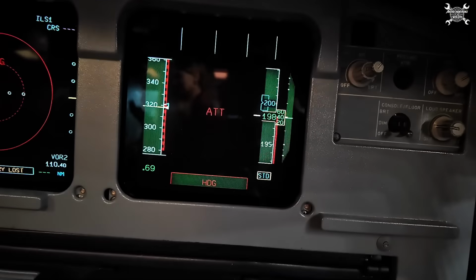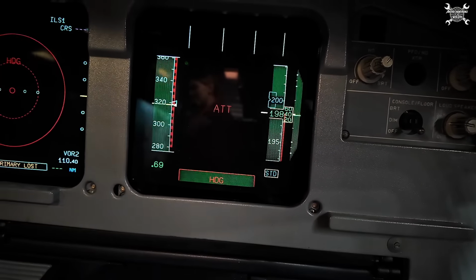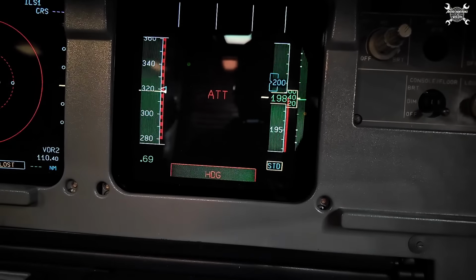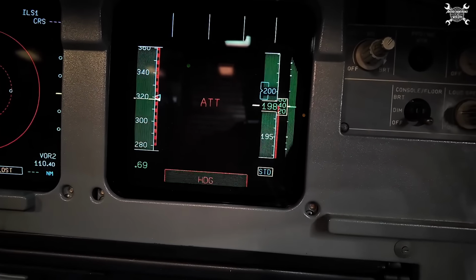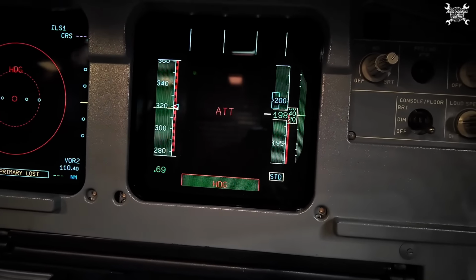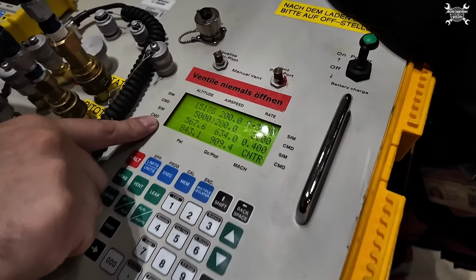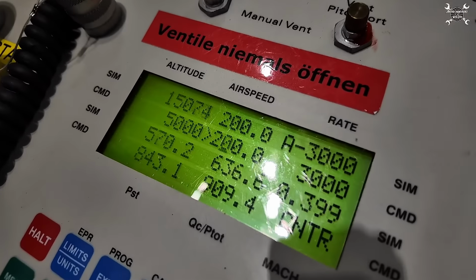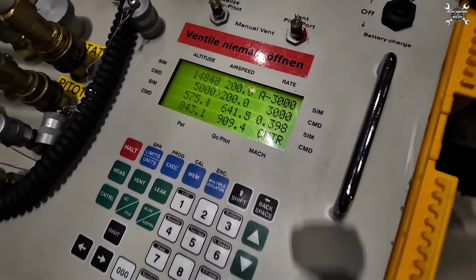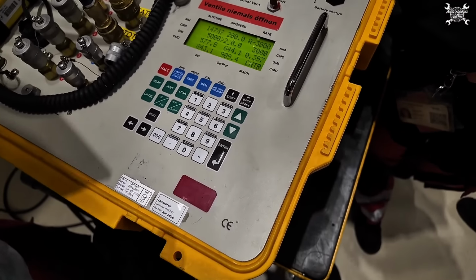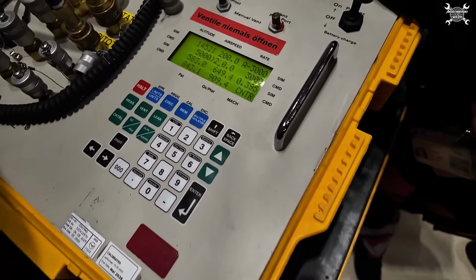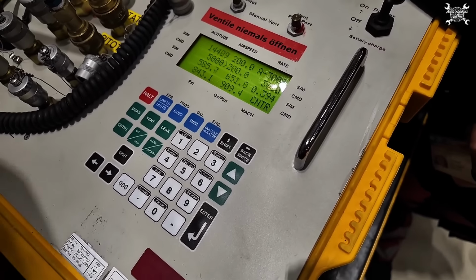Okay, so after 5 minutes we dropped like 2 knots from the speed, and let's say 160 feet from the altitude, which is in limit. So leak check for 5-minute pass. You have tests where you have to go for 40,000 feet. Yeah, so if you have a leak and it drops immediately,